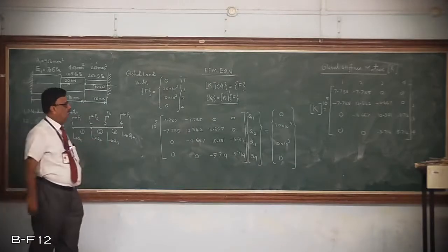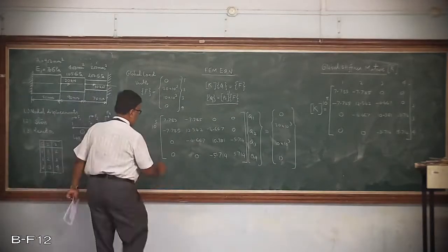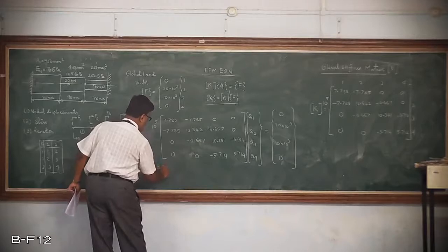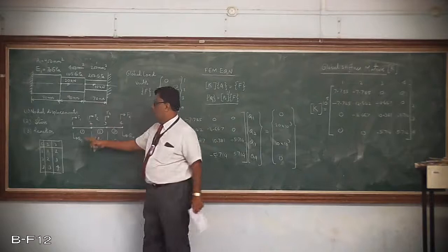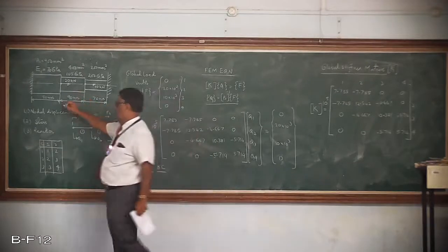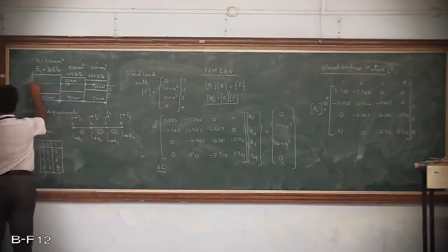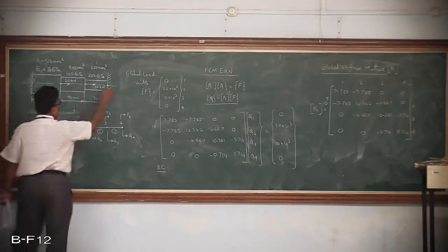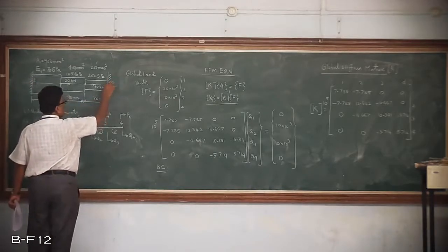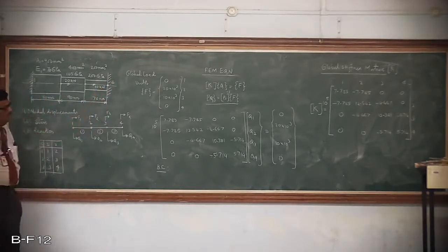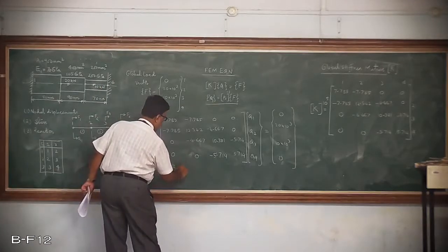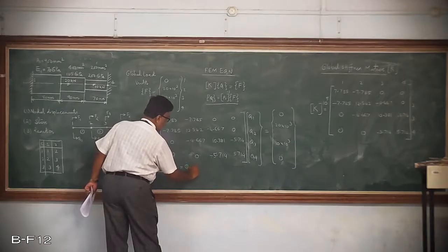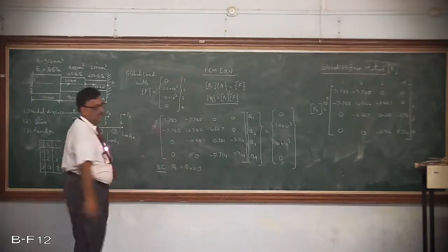So since this is not possible, we are adding the boundary conditions. Okay. Now, what are the boundary conditions? Let us see here. If we look at the figure, the node 1 is fixed. Here, this being the node 1, this is fixed. That means the first degree of freedom is fixed, and since this fourth node is also fixed, so obviously Q1 and Q4 are equated to 0 because since they are fixed, there is no motion, so these are 0.